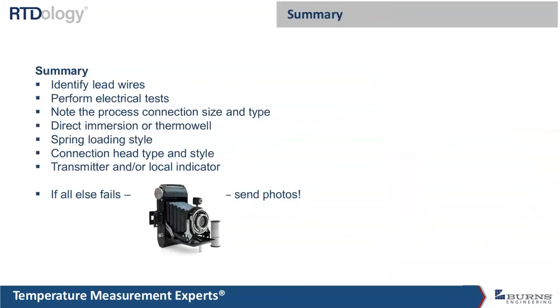So with that, just to kind of wrap things up here, and we kind of went through it pretty quick, but when looking at an RTD or thermocouple, identify the lead wires, the number of wires, and the color. We talked about some electrical tests, just a resistance check in an ice bath or at room temperature. We have typically about 109 ohms at room temperature for an RTD.